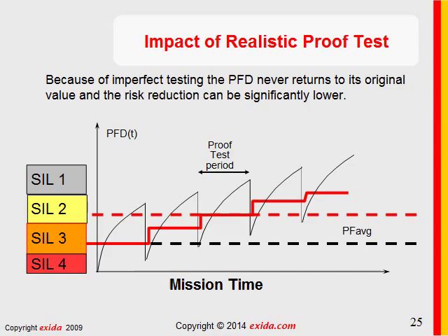Although a lot of people think, hey, if it works, it works. All I have to do is, for example, run that pressure up, make sure the valve attempts to close. You just won't believe how crude some of the proof tests are. One of the most obvious examples is if you do a proof test by putting a block on a valve, checking to see if the valve attempts to move, you have no idea if the seat actually seals or not. So that's far from a perfect proof test. I only picked that example because it's so obvious.